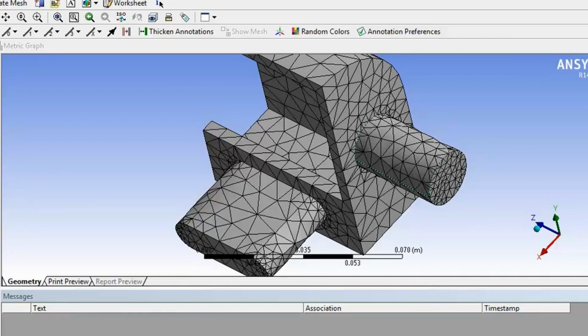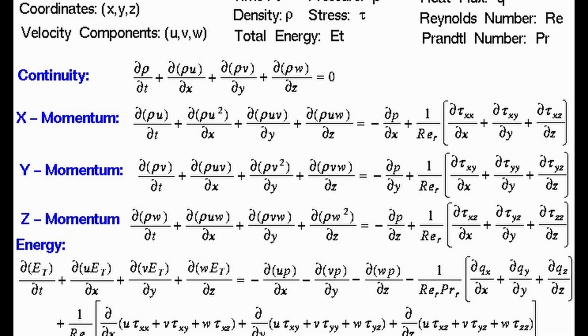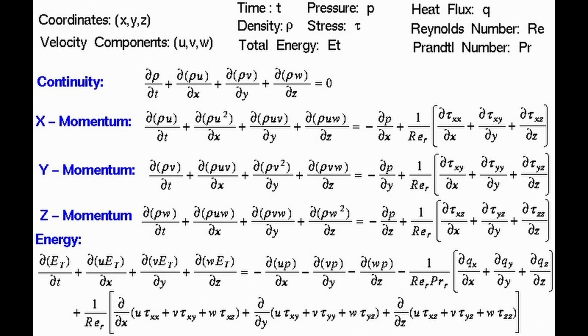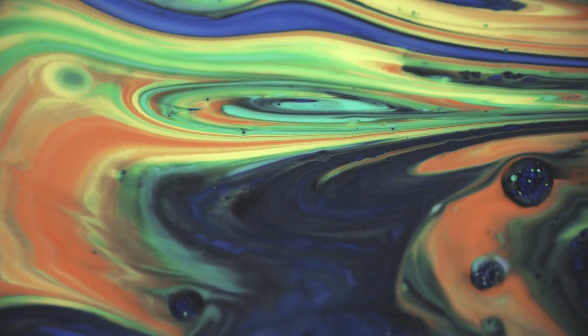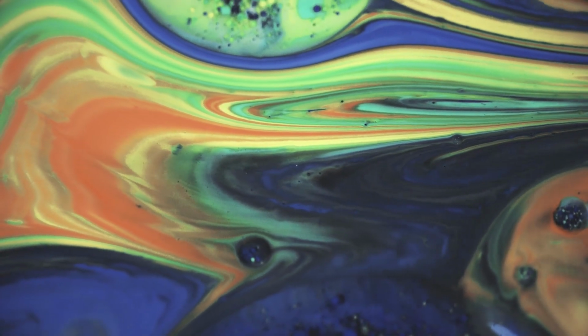Both conservation of mass and conservation of momentum equations together are called the Navier-Stokes equations, and these are partial differential equations, and both equations are highly coupled. That means you cannot solve one without the other. Also, these are non-linear equations, which makes them near impossible to solve. To convert these non-linear equations into linear algebraic equations, which are easy to solve, different methods or approaches are used